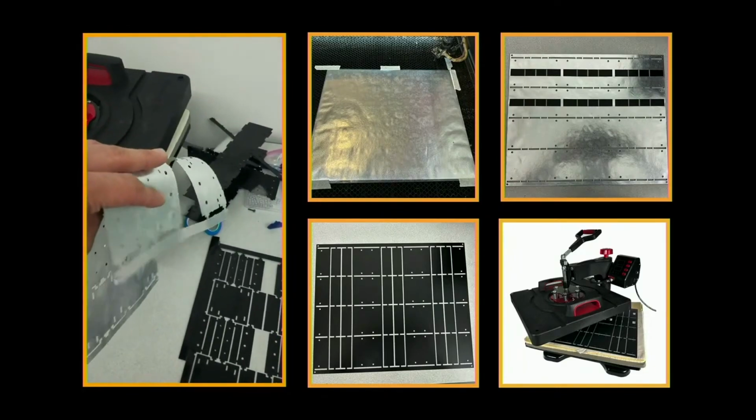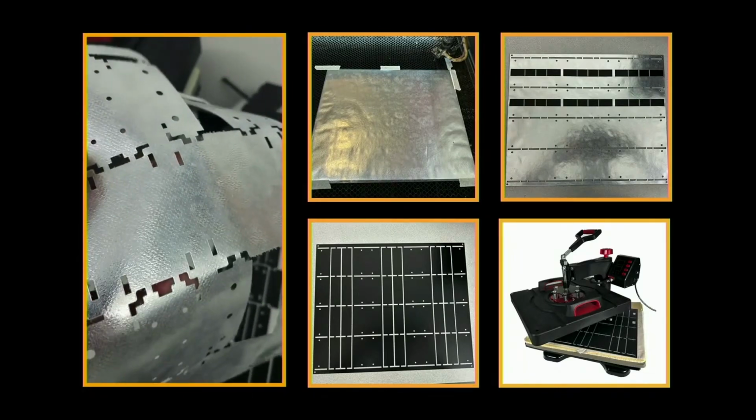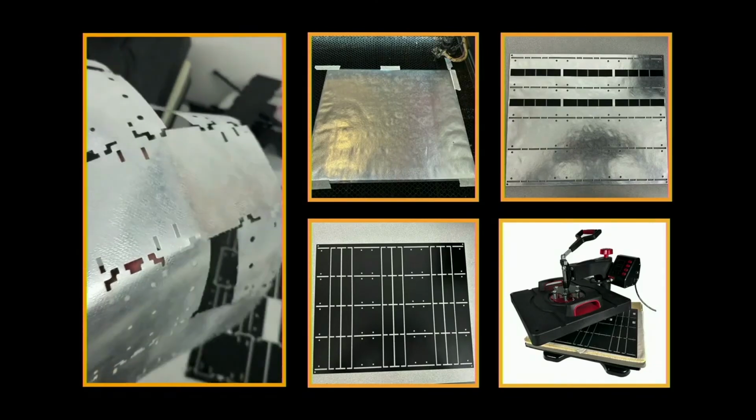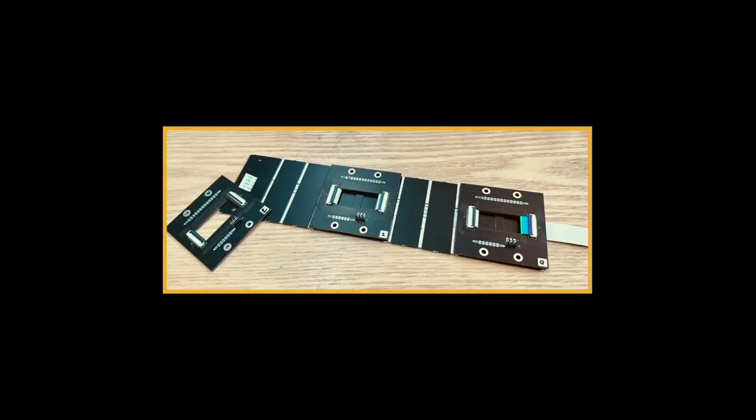On the left side, you can see that's our Mylar and adhesive, which we've pre-laminated, and in this case, pre-cut. We lay them all up there, squish them all together, and then we cut our sheets into these strips. We add these jumper boards, which mate with those internal flex cables. This is how we join one cell to another, but this is also how we join one strip to another. So this is how we get to these 2-meter-long columns from that initial panel, 15 inches or so, square on each side.